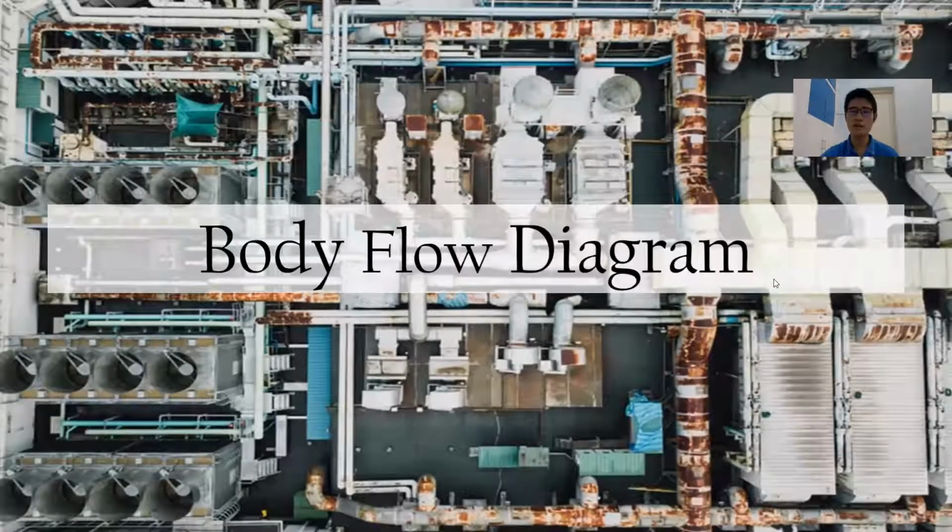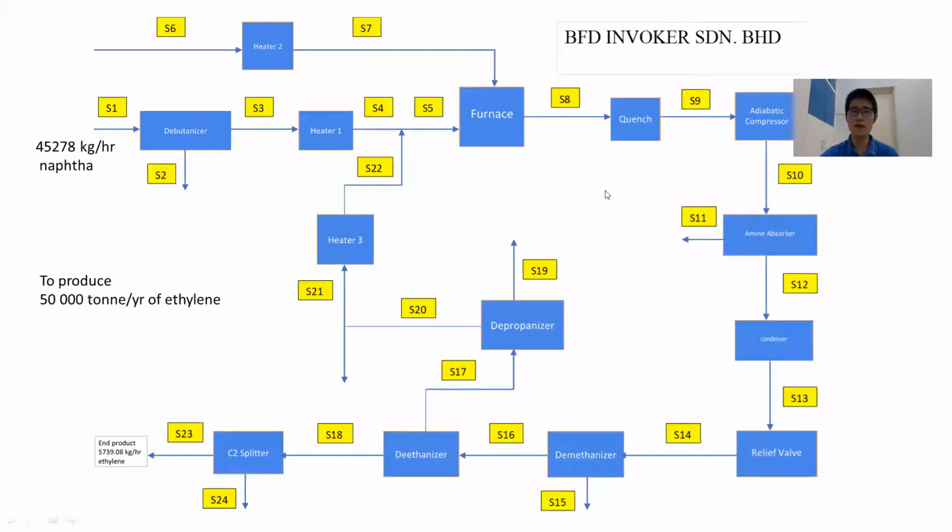So this is our company's block flow diagram. Basically, we are going to produce 50,000 ton per year of ethylene through the C2 splitter, which is the last unit. The end product will be at the distillate of the C2 splitter. Firstly, the naphtha will enter into the debutanizer to separate the butane from the other components of the naphtha.